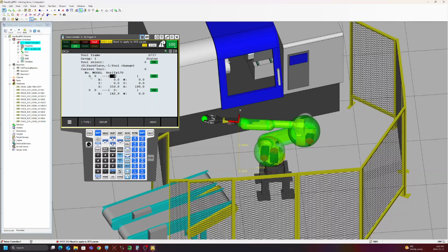I will bring the data from the standard one to the DCS tool frame. My tool is number 3. If you see, I have my Z offset and also the roll orientation. It's previous, and now we set our DCS tool frame. We will use it for the user model and also for some other functions like the tool change function and all of the stuff.